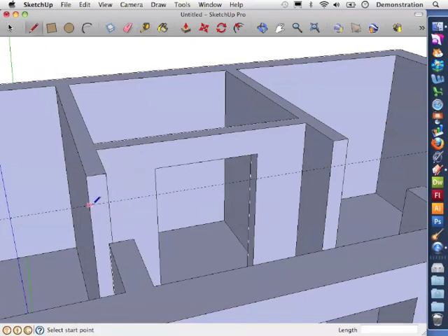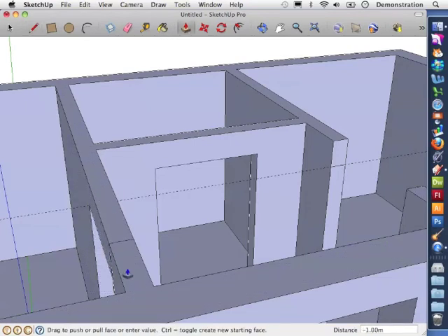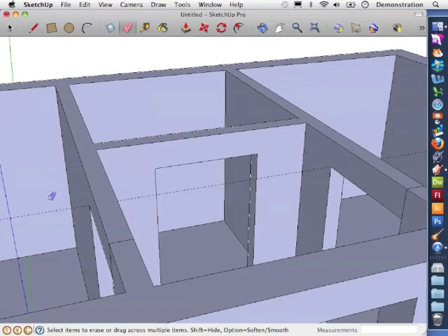And then I will get my pencil tool again, the line tool, and just click across. So we've got the markers at the top of the walls. I'll do the other side while I'm here. Let's get the push-pull tool and pull those so that they join. That's one. And do the other one. And again, the eraser tool and remove the unwanted lines, which includes the guideline, because we've now done all the doorways in our bungalow.